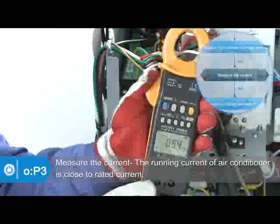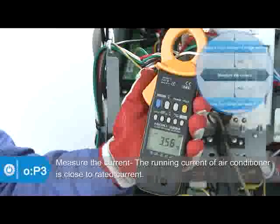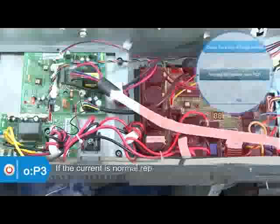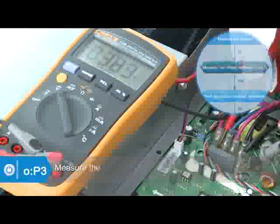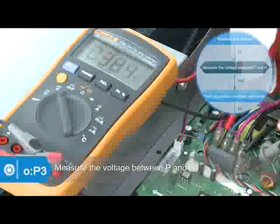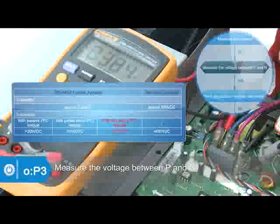Use a clamp meter to clamp the live wire to detect whether the running current of the air conditioner is close to the rated current. If the current is normal, replace the outdoor main PCB. If the current is abnormal, measure whether the voltage between P and N is normal. For the normal value, please refer to the table.